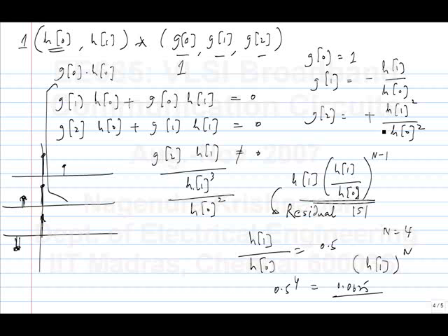Let's say I know the channel response. I decided that I'm going to use a 4 tap FIR equalizer, and I want to determine the coefficients of these taps. What was the basis here? How did we determine the taps? So we cancelled out all the inter-symbol interfering terms as much as possible. I mean, the ones at the ends obviously we cannot cancel. Okay. So is that the best we can do, or is there some other thing that we can do?